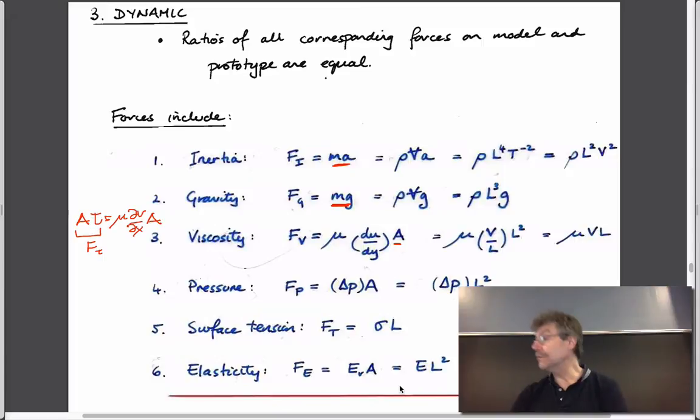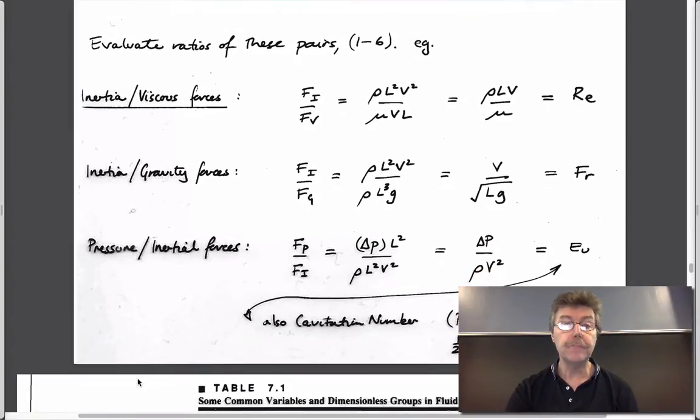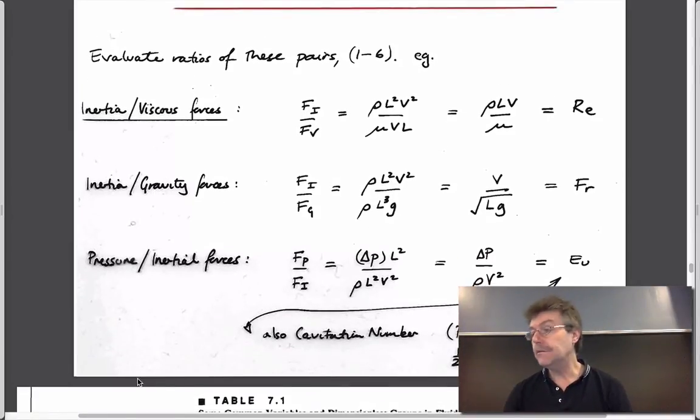And likewise, when we talked about designing bridges so that they don't become galloping Gertie, as in the Tacoma Narrows Bridge, and self-destruct, we can also look at aeroelasticity in structures and in planes, where the key parameter is the flexibility, the elastic modulus of the system. So in this case, we have 6 individual force terms. We could look at every single permutation and combination of those to look at important terms. And so we could do what we did with the Bernoulli equation from a more raw standpoint, to look at the Reynolds number, which by definition is just the ratio of inertial to viscous forces.